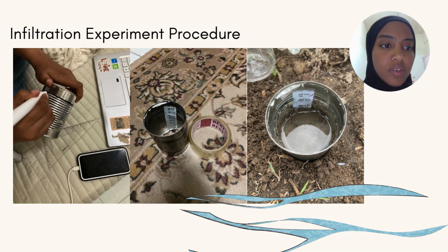We inserted the ring into the ground in an open soil area with no grass. Then we filled the ring with water up to the 5 centimeter mark and used a stopwatch to record how long it took for the water to absorb in the soil.